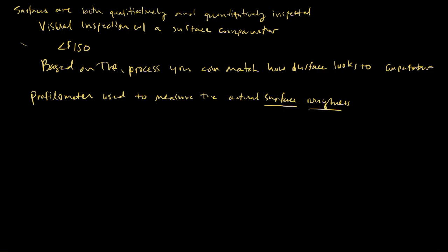All right. So if you have a surface, and the surface looks like this, and you have a profilometer with a nice round tip, then as you drag the tip over the surface, it's going to rise and fall along these edges, and you're going to get data. If you're measuring this vertical displacement, you're going to get some data that will look like this.